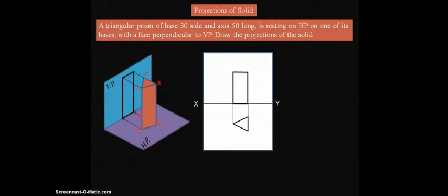We have drawn the rectangle with the help of the projection lines from the top view and the axis of the prism. Now look at the center point. To find the center point, you need to draw the bisecting lines of the angles for any two corners.